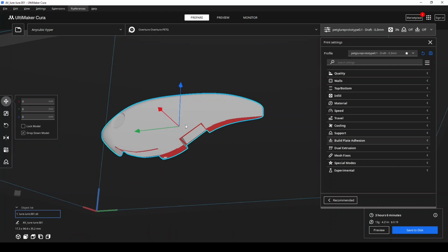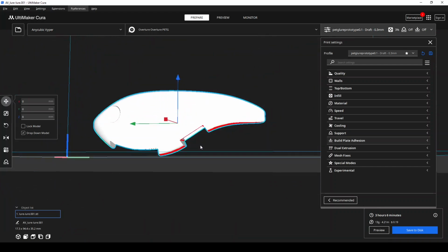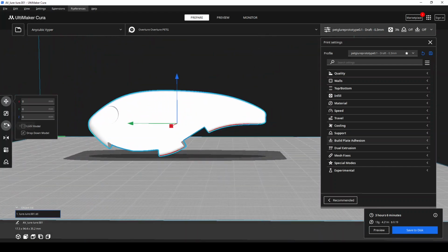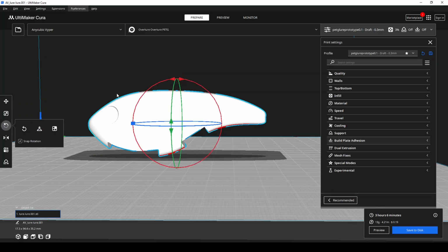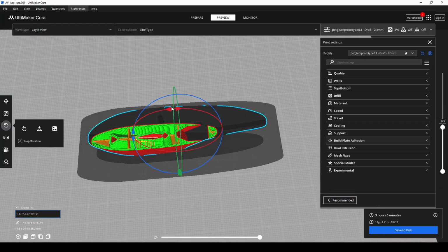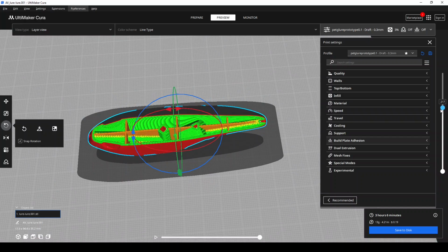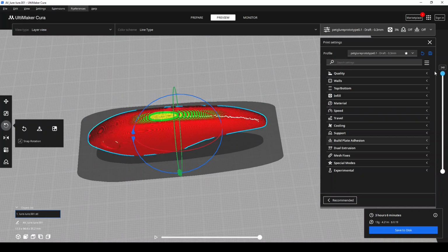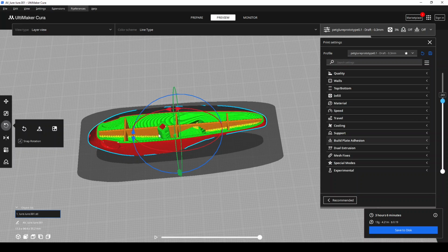I don't like messing with the supports right there, and that is one reason I like to print my lures upside down. Another reason is, depending on the infill you use, you're going to need to support the top a certain kind of way. So you're not going to want to go here. If I had lightning infill or something, it would be really filling it up here. You would need a higher percentage infill than what I have here in order to get a clean top.